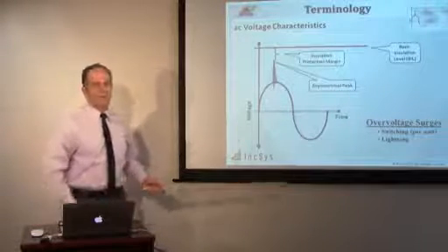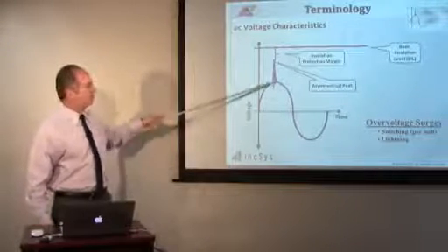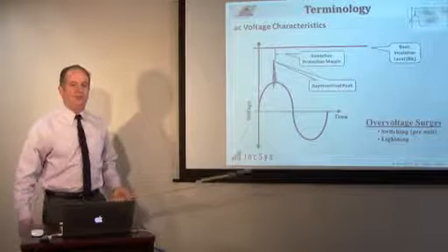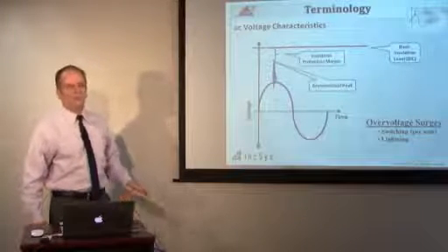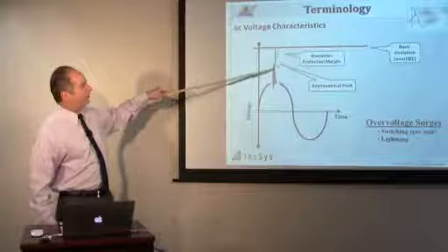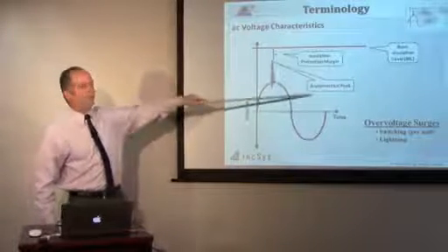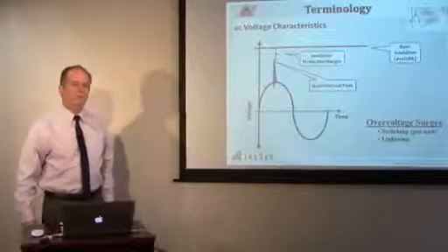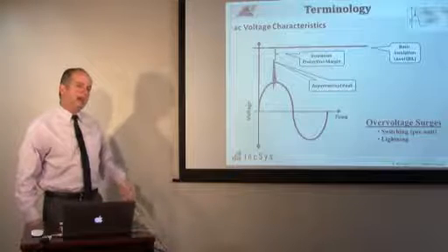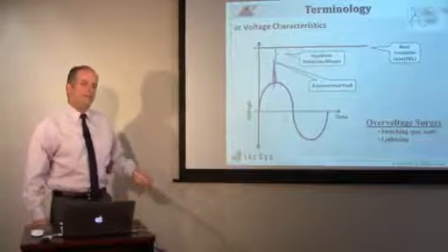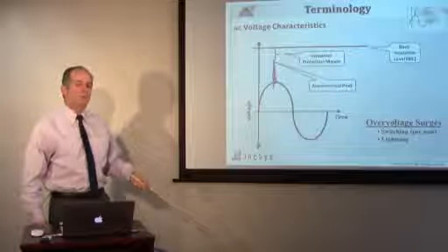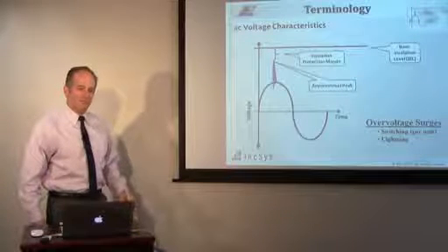Another important aspect of voltage to know about is when there are transients on the signal, which happens in a power system or electronic systems. When there are transients, we refer to those peaks as the asymmetrical peak. That asymmetrical peak is the highest voltage peak. Now, it might be there momentarily, but it has the potential to damage or puncture through insulation.